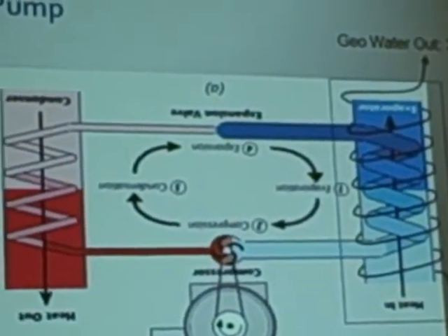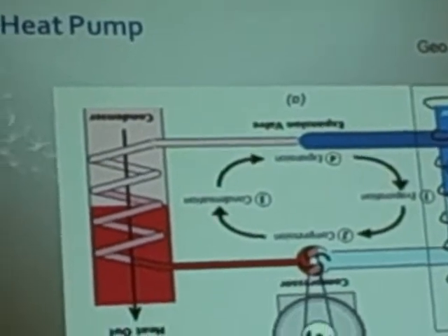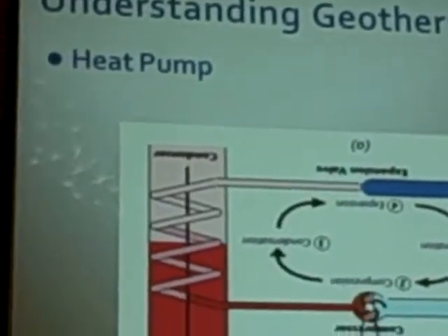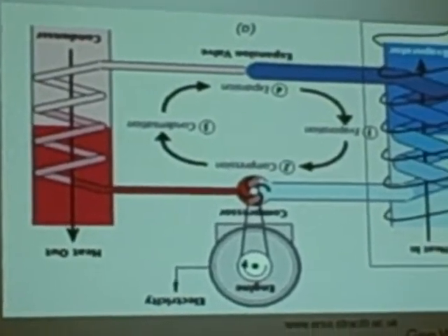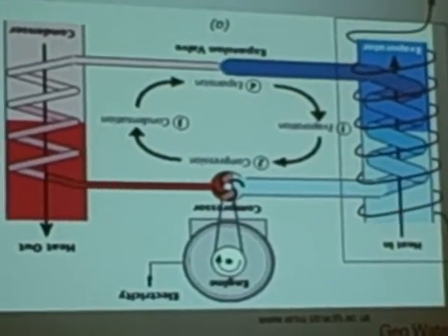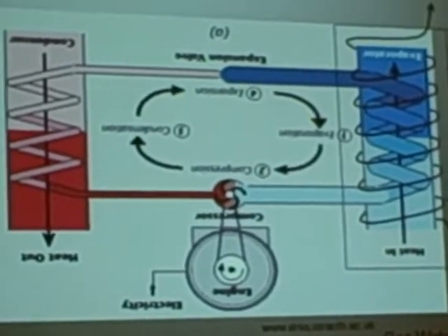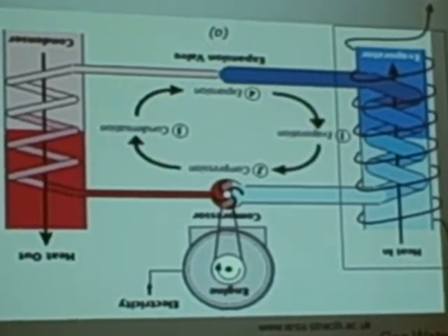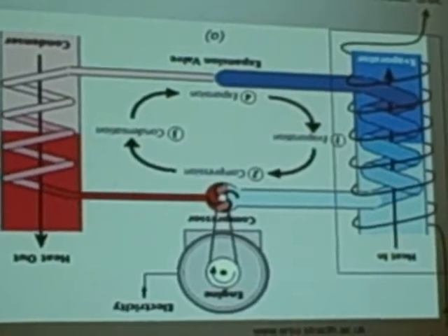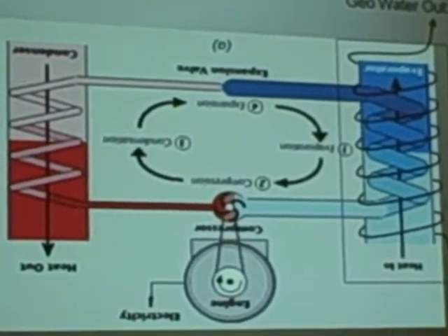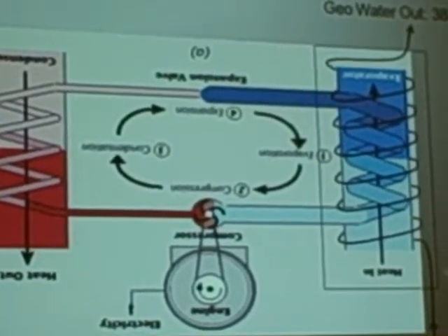and the process continues. So when you flip, on your thermostat, that little switch from heating to cooling, there's a reversing valve in there that's just basically switching the valves across, and you're reversing the refrigerant flow within the heat exchanger. And that's all that's occurring. But it's the exact same process. We're expanding a gas, we're compressing a gas, and we're using those two principles to either wash heat off the heat exchanger or add heat to the heat exchanger.